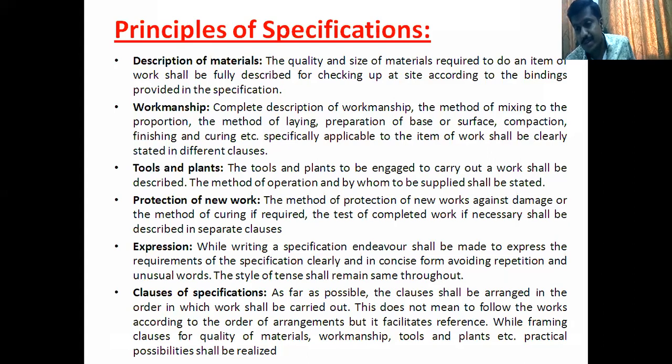Or I have mentioned I am going to use only vitrified tiles in your hall, kitchen and bedroom. Whether you have done it according to the specifications and the contractual document, you have to check it. How to check it? The description of those tiles has been given in your detailed estimate. That is the description we require.